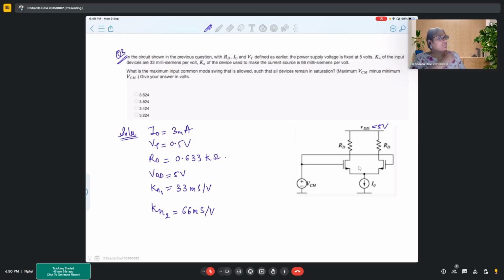Okay. First of all, when we talk about ideal current sources, there is nothing called an ideal current source. All the current sources are designed. When we say we are using a current source, we basically use a transistor or a MOSFET in saturation, because in saturation it gives us a current source kind of behavior, that is constant current behavior.